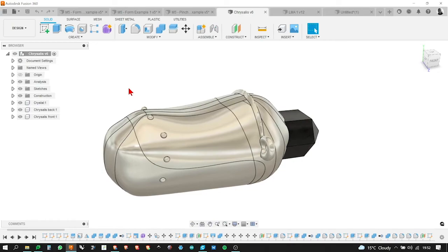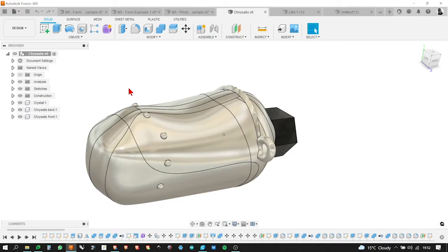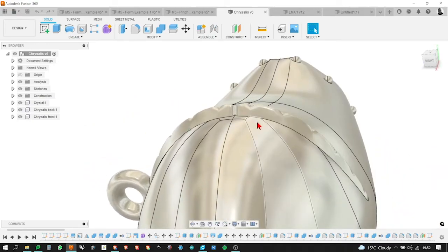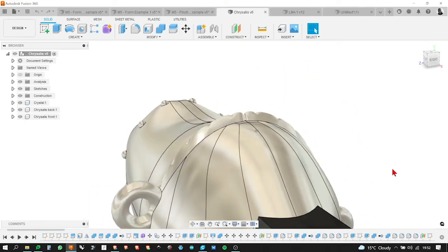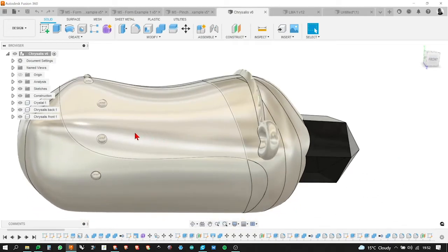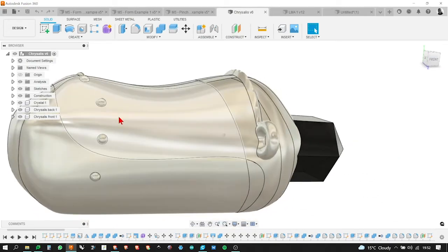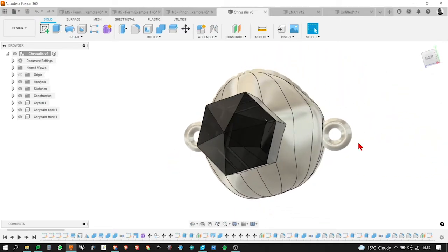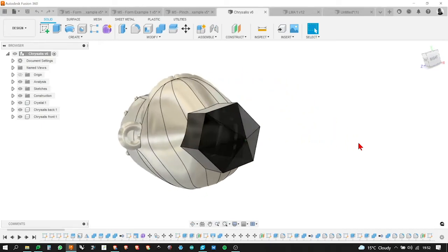It's quite a complex shape, which we could have had a go at lofting, but it's very biomorphic, very organic, and this is just a representation. It wasn't massively accurate, but we had this interesting ridge with dips or notches in it, which were in this chrysalis. It had these little bumps in it, but we could also pop in quite nicely, using a torus primitive, some little loops for holding the chain, because this was a pendant.